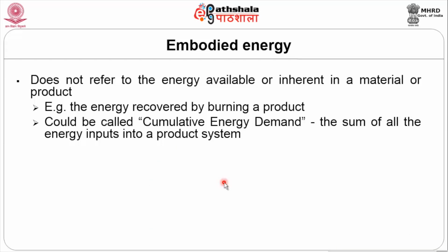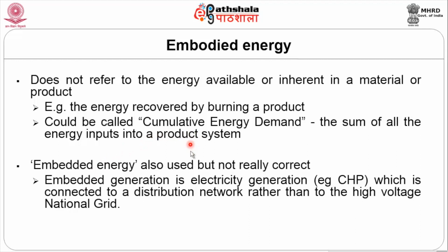Embodied energy, many people will have a wrong thought. They think it is available energy or the energy it produces. People always refer to it as energy available or inherent in a product, for example, the energy recovered by burning a product. It can also be called cumulative energy demand, that is nothing but the sum of the energy which is inputted in the product system. But this kind of understanding of embodied energy as energy inputs in the product system is not correct.